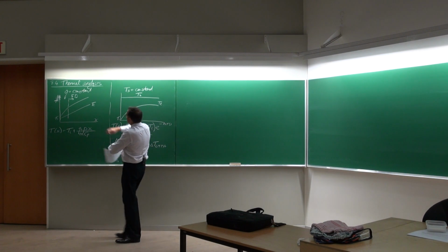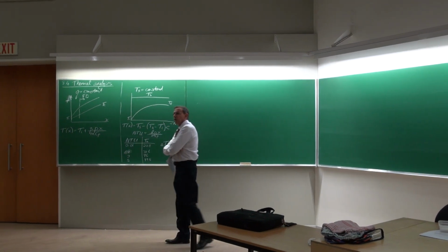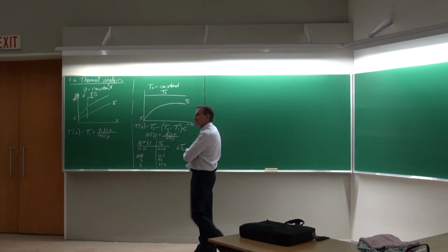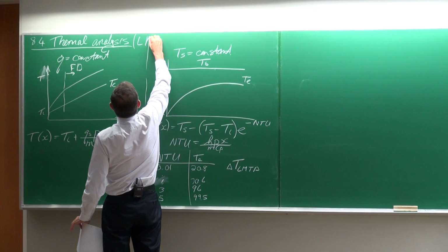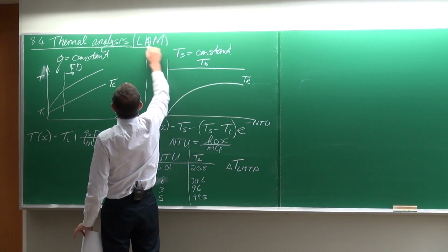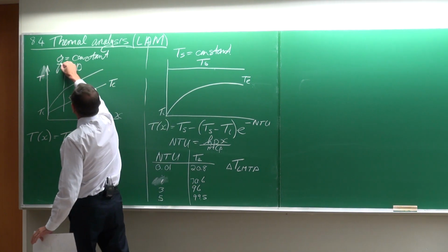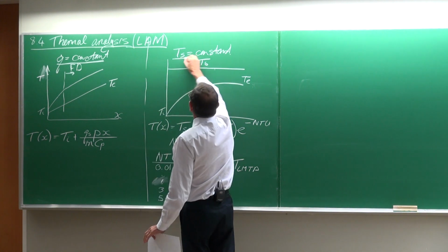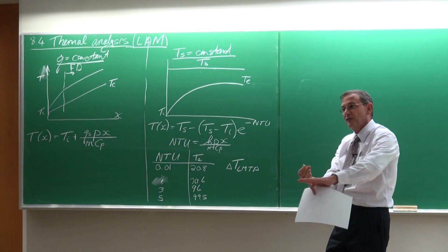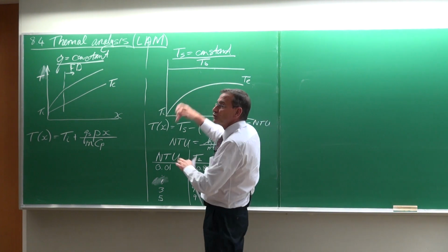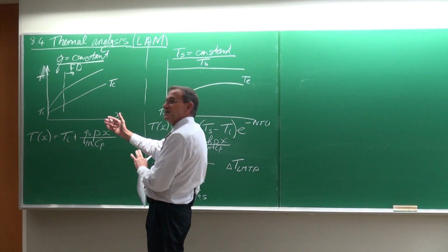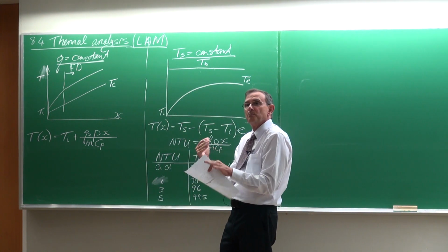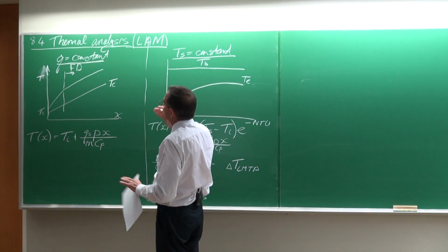Just going back to the previous lecture, which was in general paragraph 8.4, a thermal analysis, we've said that specifically when we consider laminar flow, it is very important to distinguish whether the heat transfer is at a constant heat flux or if there's a constant wall temperature involved. Of course, the characteristics of the heat transfer processes are quite different.